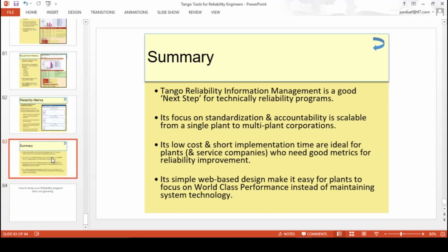It gives you a lot of ability to track a piece of equipment, to track vendors and repairs, and how well vendors are performing for you. It gives you the ability to look at types of equipment and see what the life is in terms of MTBF and root cause of failures, and over time how you're affecting that. So lots of good things come out of equipment tracking, but it's hard.